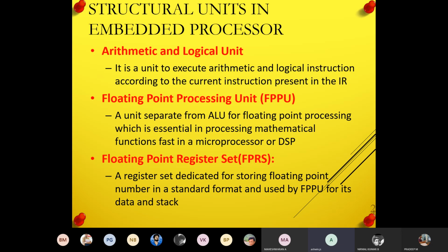And the floating point processing unit. I told you the arithmetic and logic unit works on binary values and does not handle any decimal value. For example, if I take the value 2, its binary equivalent is 10. Suppose I want to do an operation with 2.2, the ALU cannot operate on it. At that time I use another processing unit, the floating point processing unit, to perform operations on numbers having a decimal point, like 2.2, 1.3, and so on.